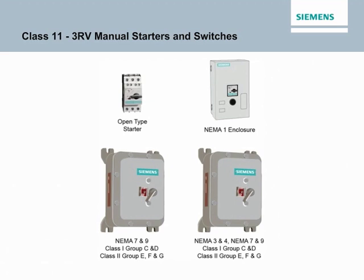Class 11 3RV switches provide control where overload protection is not required or is provided separately. Class 11 3RV controllers are available with low voltage protection, which automatically opens the power poles when the voltage drops or power is interrupted. They are available in an open style without enclosure, in a NEMA 1 general purpose enclosure, and in NEMA 7 and 9 or NEMA 3 and 4 enclosures for hazardous locations.